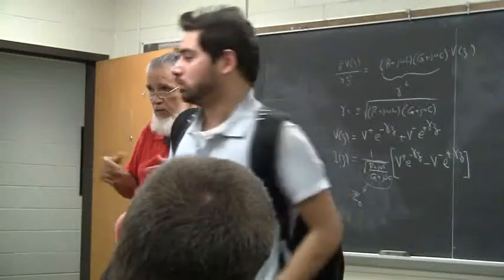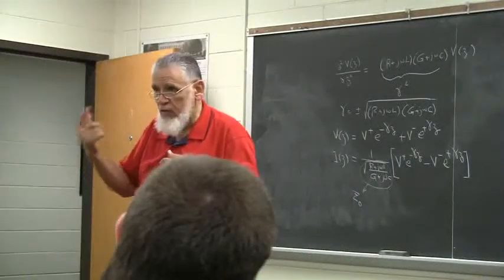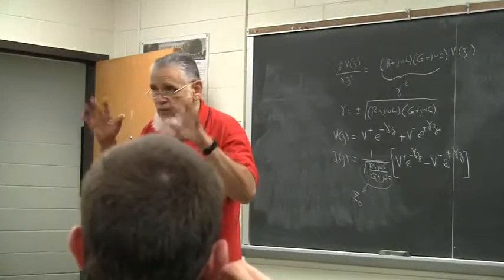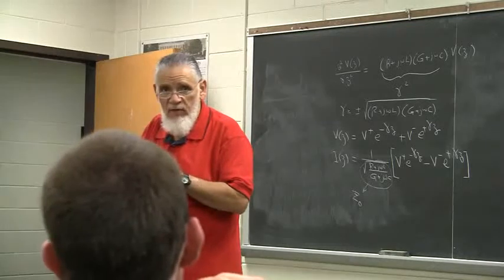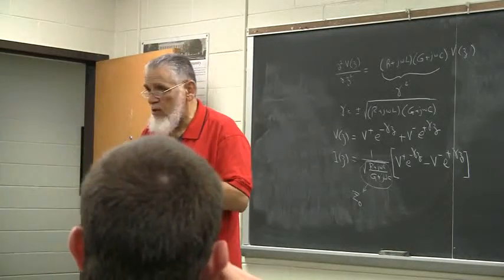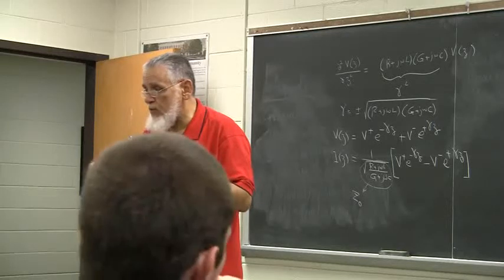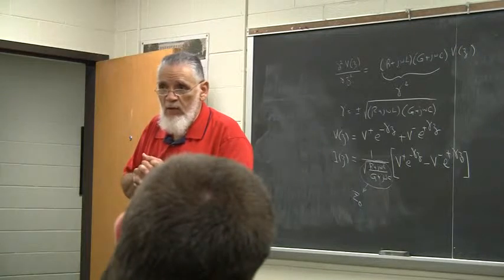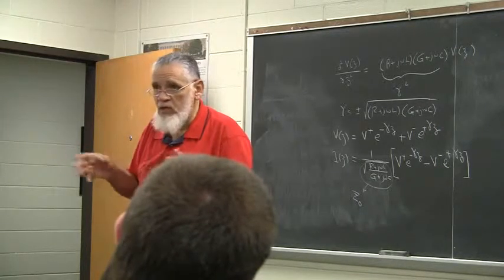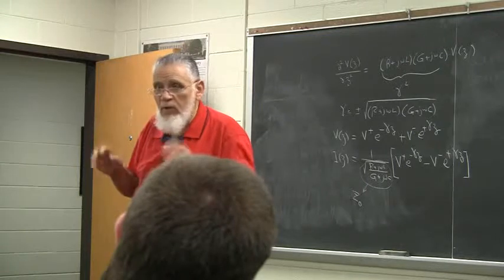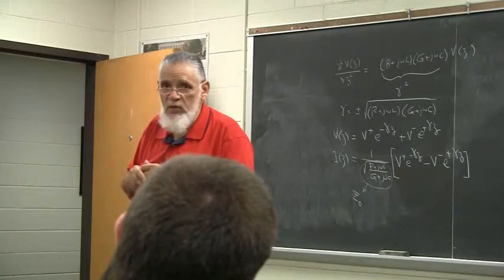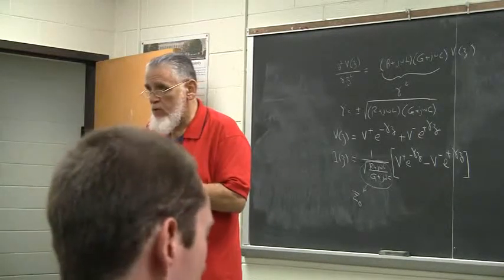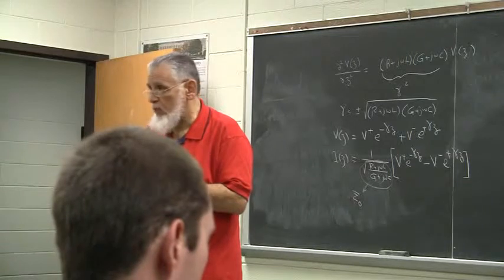We recognize some inductance, some inductive behavior. You've got yourself a magnetic field, so there's some inductive behavior. There is some electric field, so there's capacitive behavior. And there's a dielectric that is never perfect, so there's always a leakage through that dielectric, the conductance of the dielectric, and we call that the conductance. So I have RLCG. These are the simple approximation to the behavior of the transmission line, and we can actually use them to develop the first order solution to the transmission line problem.